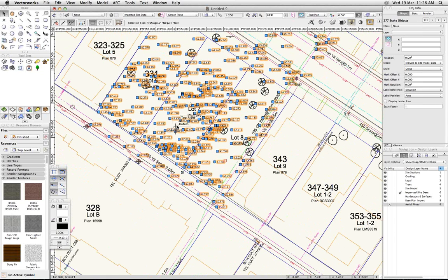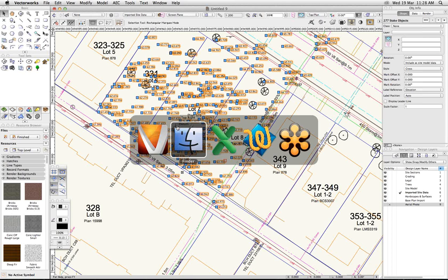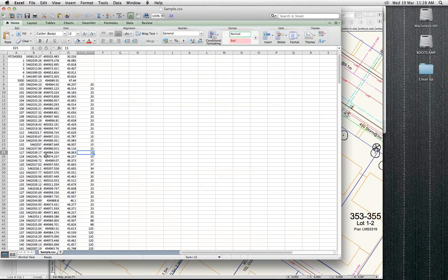Okay, so there are many small variations on how that might come to you. The DWG, the orthophoto, and these survey points. But if you just keep in mind this sort of process of taking it apart and looking at the plain text files, there's nothing really very complicated there, and it's possible to sort out most problems.